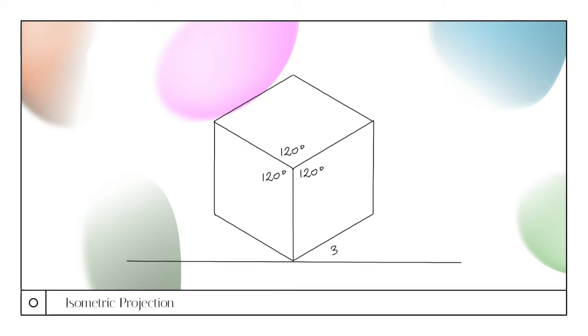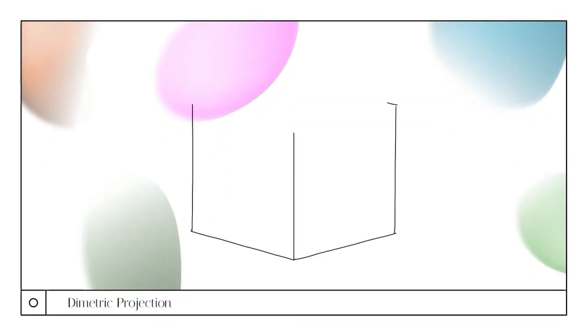Isometric projections, when measured at the corner where its lines converge at a point, its angles all measure equally, and all three principal axes are equally foreshortened. These axes will always and forever be 120 degrees apart from each other. If we draw a horizontal line in which the corners will intersect at a point, the measure of these angles will be 30 degrees.